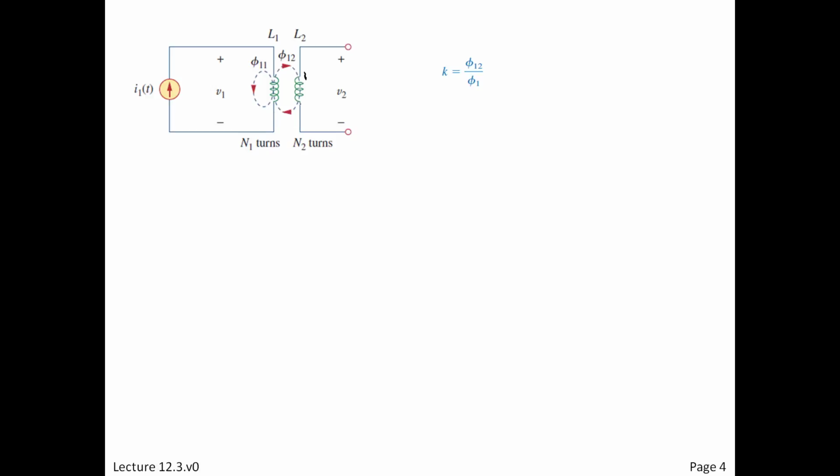And we can then, from what we just saw, describe the coupling coefficient as how much of the flux gets connected from number 1 to the number 2 side as a function of all of the flux available. Right? And this picture helps illustrate the more of it we can get from the 1 side to couple to the 2 side, the higher this coupling efficiency is going to be, and the greater the mutual coupling.